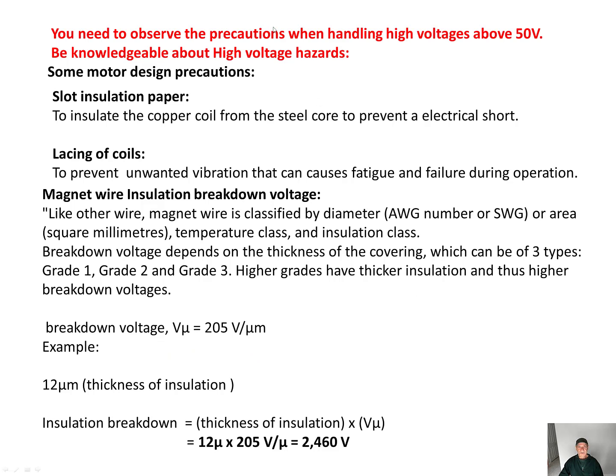You need to observe the precautions when handling high voltage above 50 volts. Be knowledgeable about high voltage hazards. Here are some more design precautions. Slot insulation paper to insulate the copper coil from the steel core to prevent an electrical short. Lacing of coils to prevent unwanted vibration that can cause fatigue and failure during operation.